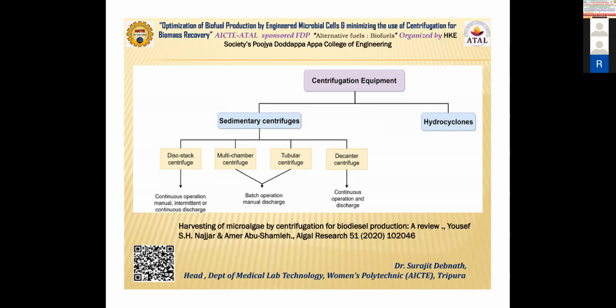You will either do precipitation, or you will add some kind of electrolytes, divalent electrolytes like aluminum, and then the impurity will be precipitated. But in this case, you cannot precipitate it by a simple process like this. You need specialized membrane filters or specialized centrifugation. The algae generates nicely, but it is difficult to accumulate it. Understood? Therefore you need to invest a lot in your centrifugation process.